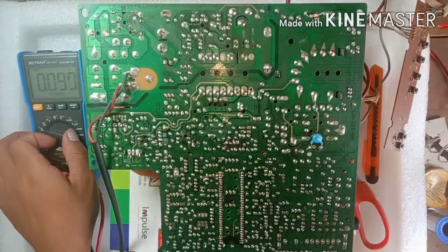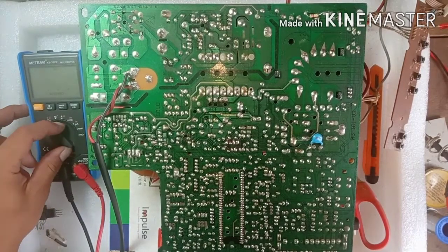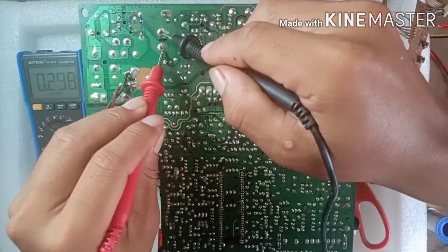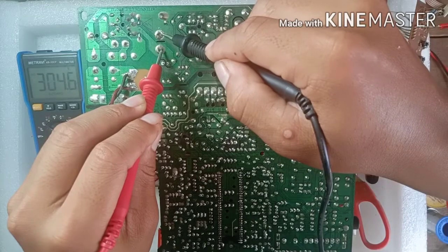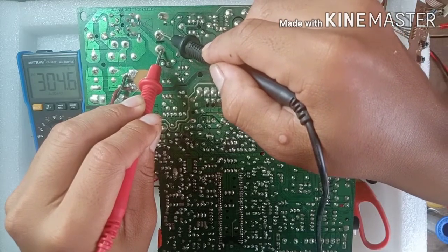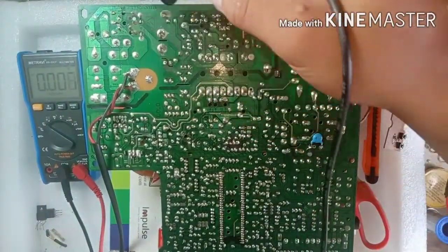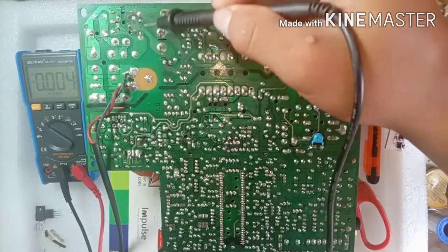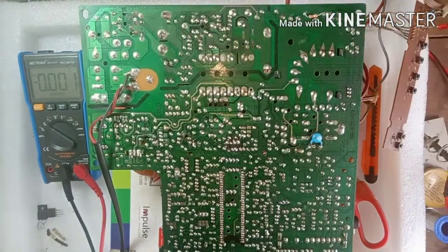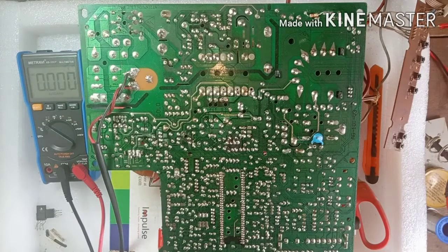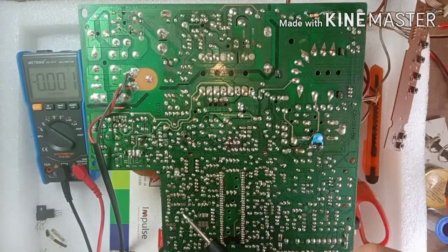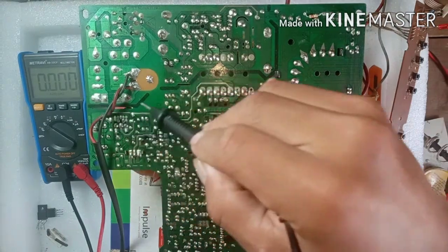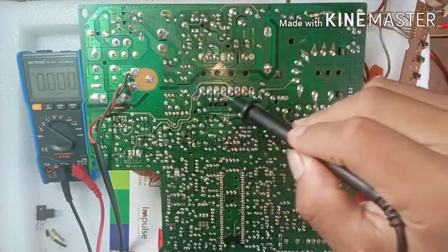Again, I'll set my meter to DC mode to check the DC output. Here we have 304 volts DC. The voltage increases as there is the full bridge rectifier circuit and the filter cap there. Actually, the signal has been totally converted from AC alternating current to DC direct current. Anyway, the input powers are totally fine. Moving on, I will now check the power distribution within the power supply section. This is the power supply section.